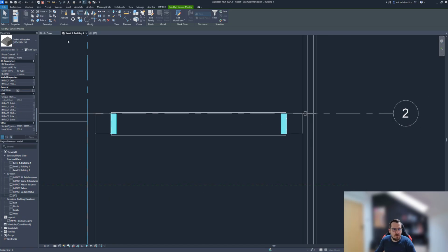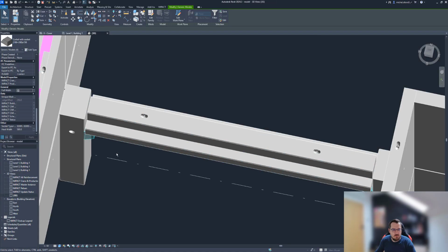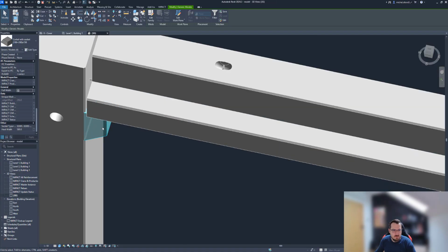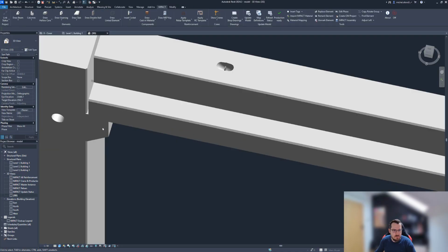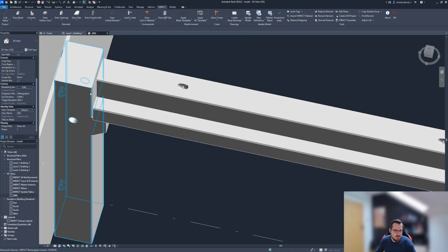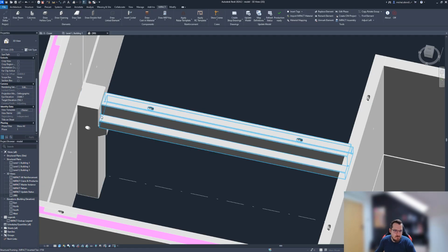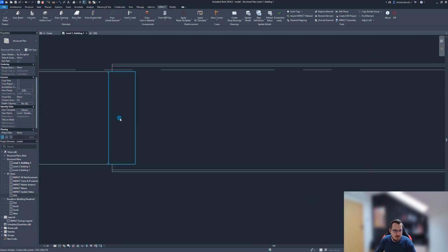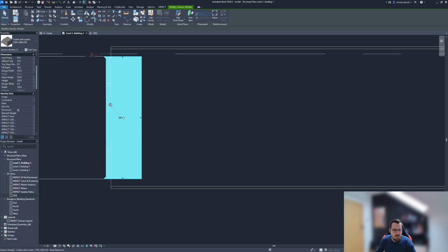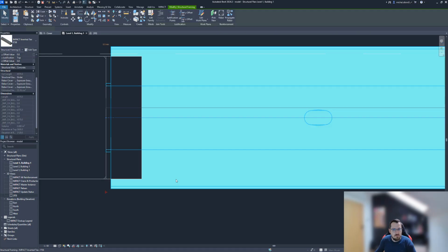And now my corbels are full width. If we go to the 3D view, we've got our corbels selected nicely and visible, and this is a nice geometry. You see the chamfers as well that we defined, and now we don't have any lifters on the corbel side, so it's there. But corbels do have a socket there, so let's edit the beams as well.